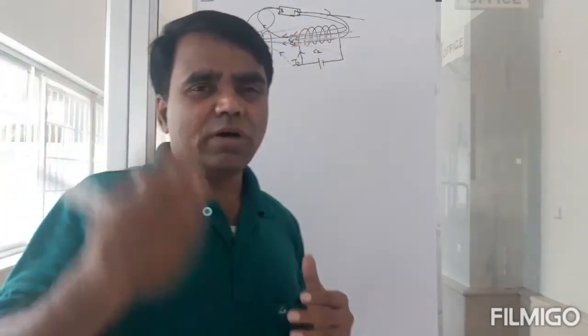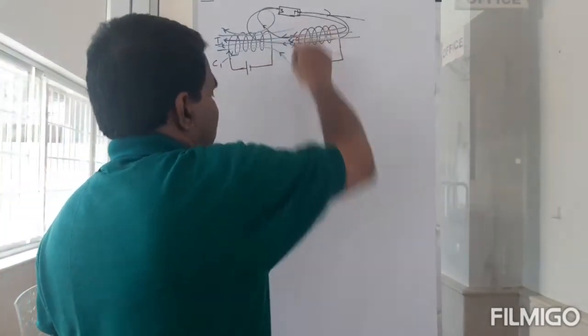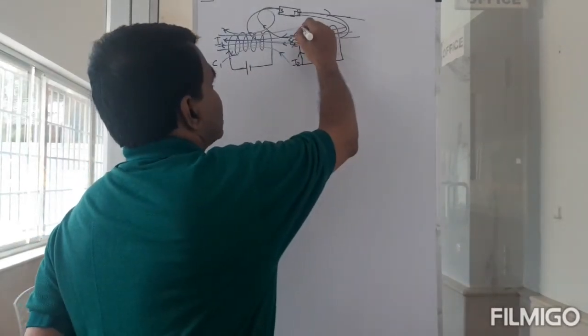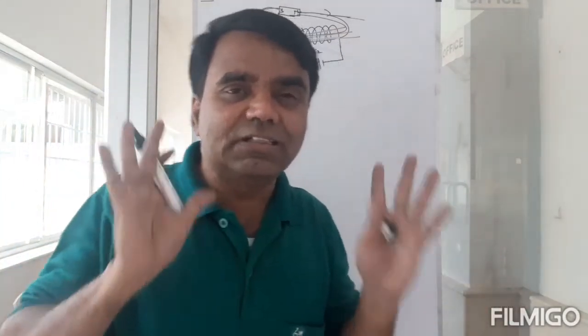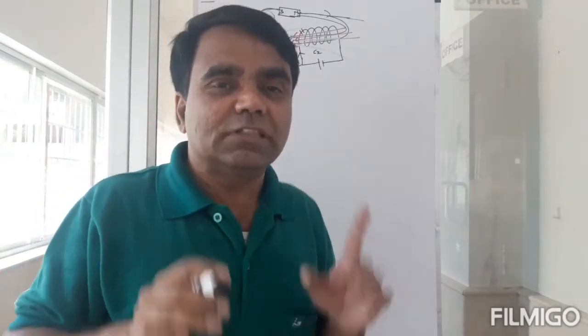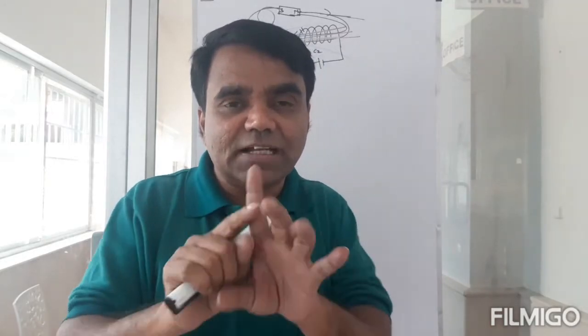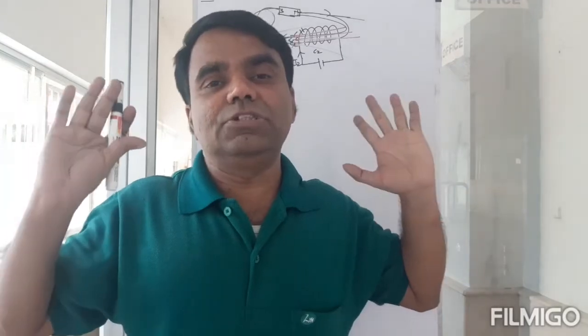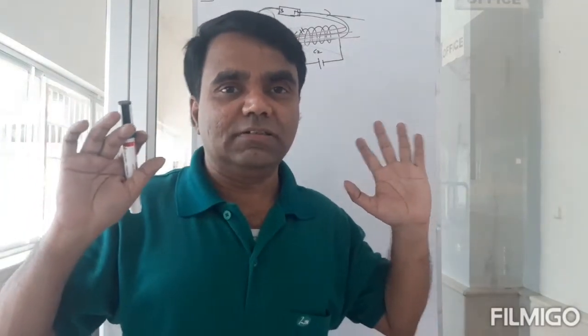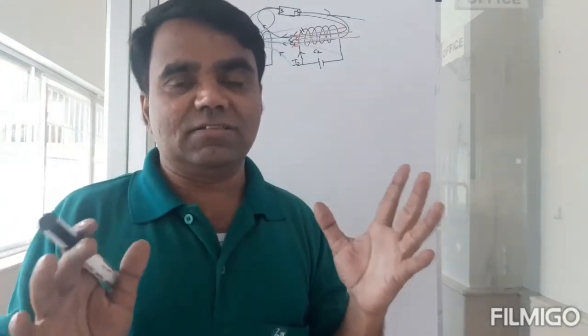But the individual coil, or even the individual current element of the coil, we take this small bit, it doesn't care where the magnetic field is coming from. What is it going to do? It's going to say this: as long as there is a change in the magnetic flux through me, I'm going to generate an EMF. That's all it does.